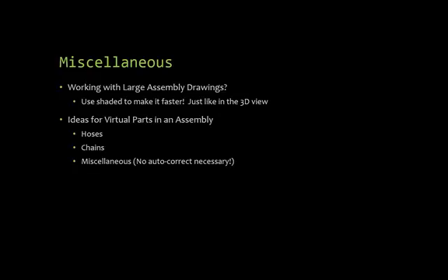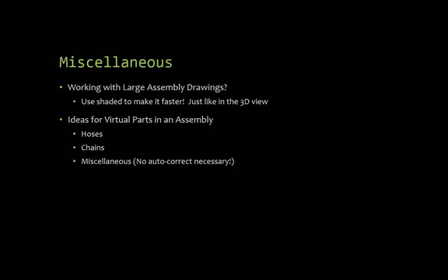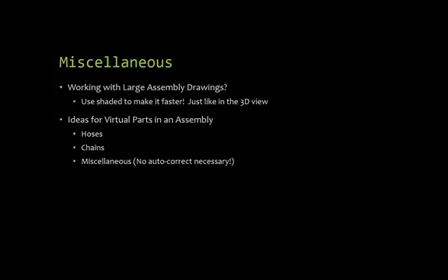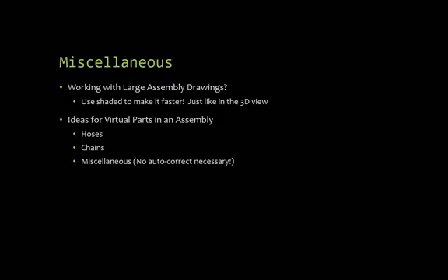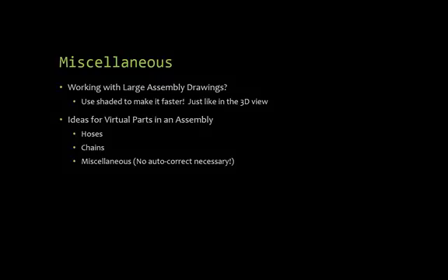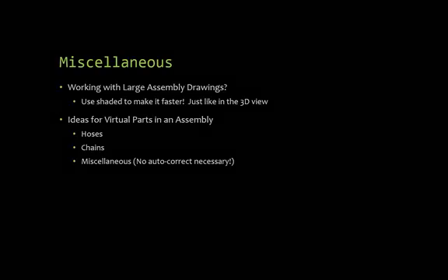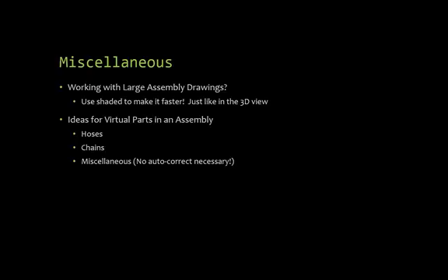So what I tell people is, it's that time debt. You're going to turn it on so that you can work on it quickly, but later on you're going to have to spend some time turning everything back to regular, hidden lines shown, hidden lines removed, or whatever. So it might take you 10, 15 minutes to go through that, but think about the time saved while you're able to work quickly in your large-scale drawing. Does that kind of make sense?